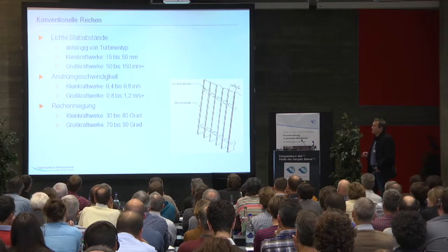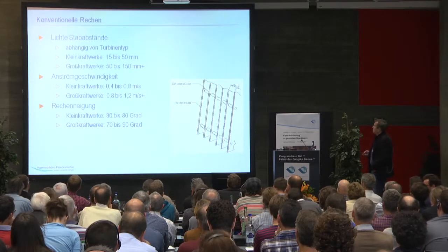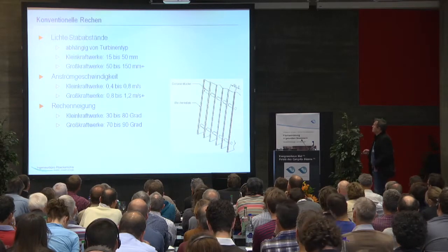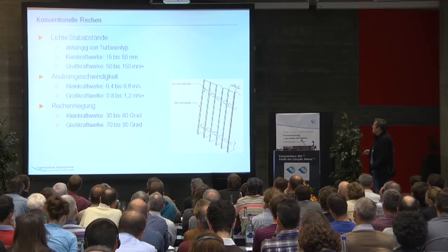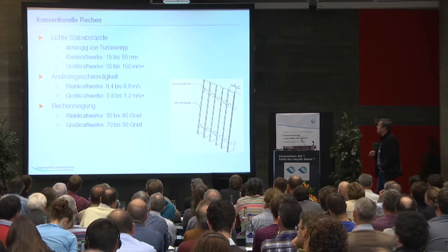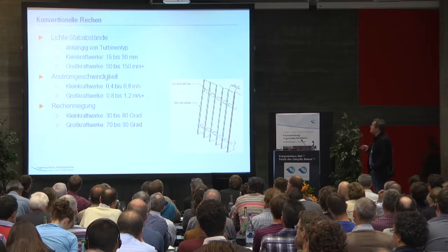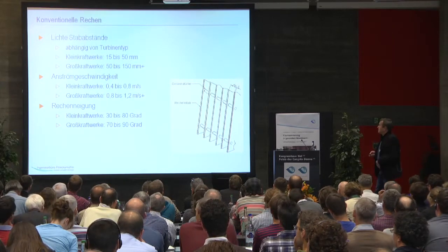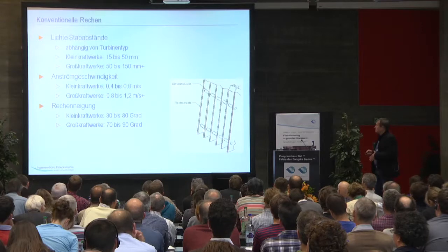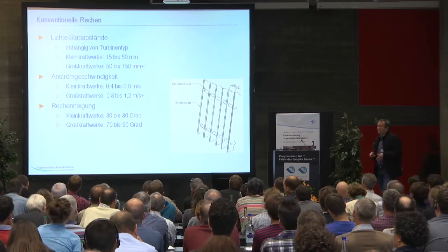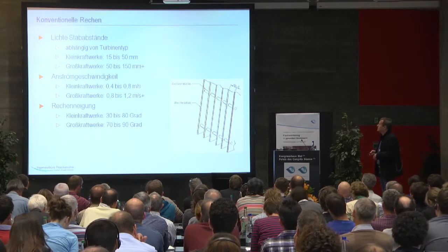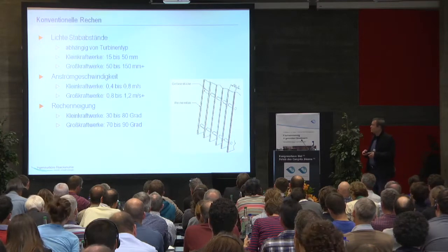And regarding the fish protection schemes for smaller hydroelectric power stations, we usually upgrade existing facilities. There we need to know that the bar distance is usually 15 millimeters, and for bigger ones 50 to 100 millimeters. And also there are differences in phase velocity, 0.4 to 0.8 meters per second for smaller hydroelectric power stations. If you have a bigger facility, they can be significantly higher.